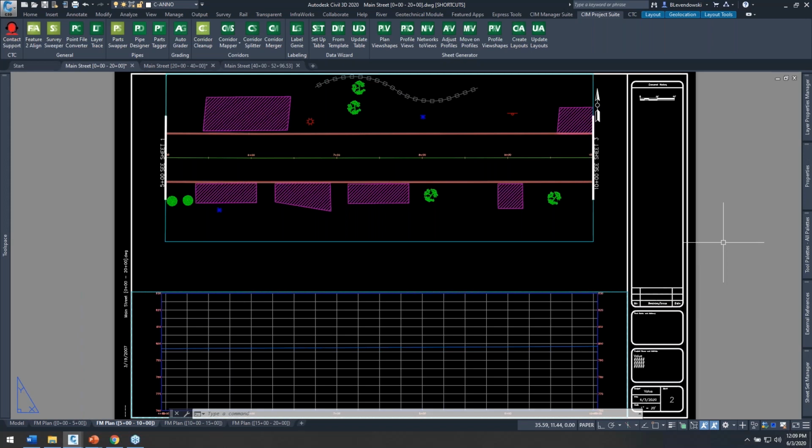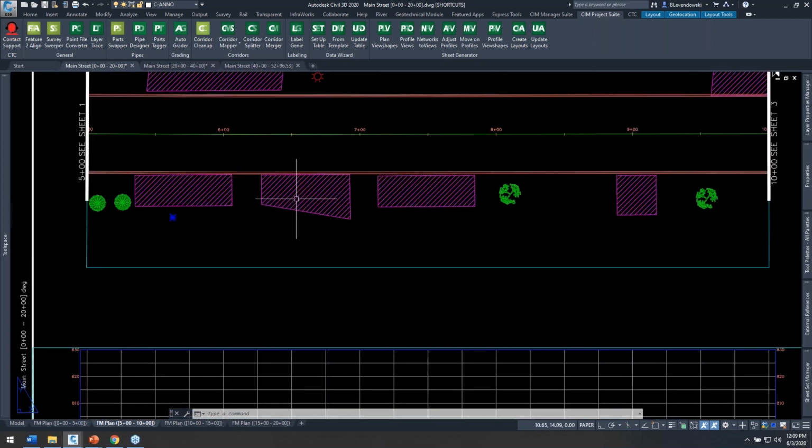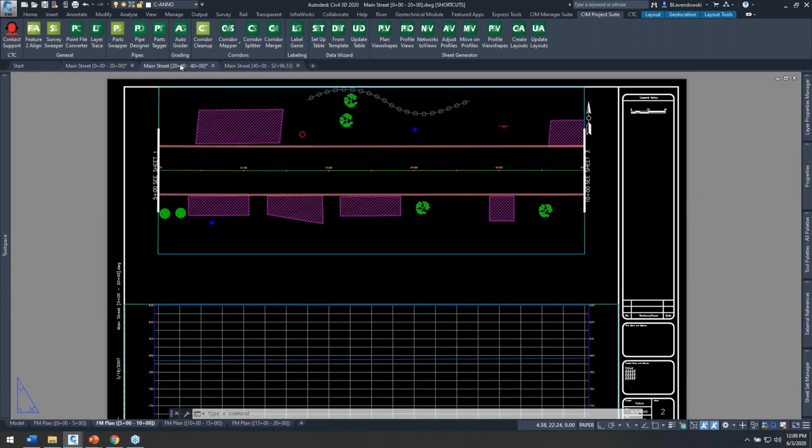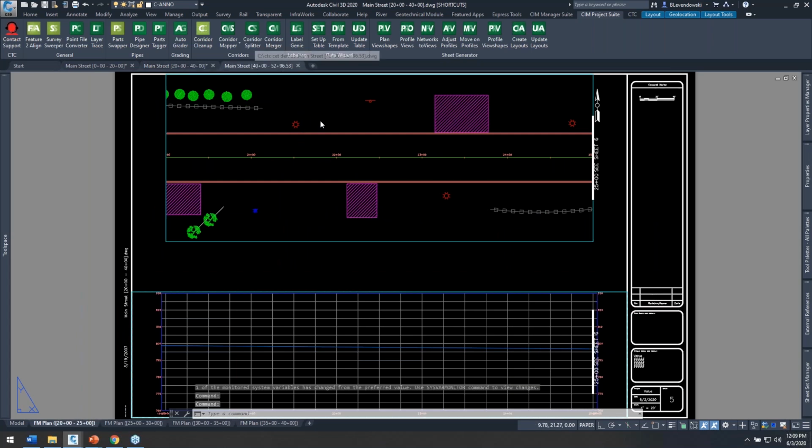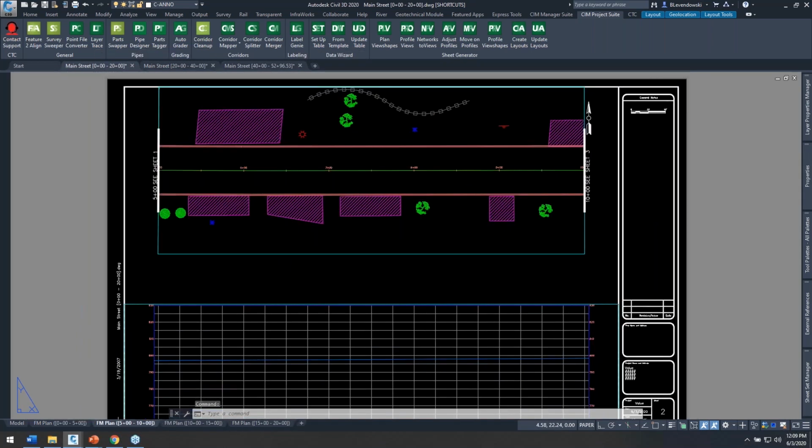We just want to label some polylines, and I want to call out the area of the asphalt to be installed in all these locations. And I've got it all over the place, right? It's across my whole project, across all these layouts. And what would I normally do? I'd put a piece of M text there, I'd insert a field on it, and then I would link it to that object and it would read that. Or I just maybe type the value in the first place, okay? Or maybe you don't even bother doing that because it's so much of a pain, right? How do you get that information into your label in the first place, okay?